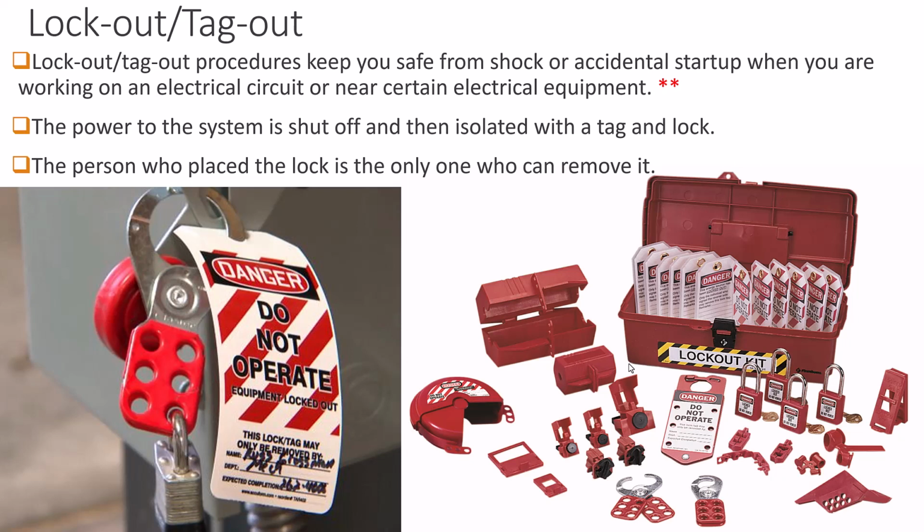But at some point, or maybe in many cases, you can only put 1 lock on a device, and maybe you can't do something like this. Well, then you can put that key inside of a lockbox, and then you lock up that key in the lockbox, and everybody puts their padlocks on the lockbox as a way to keep anybody else from accidentally, or when they're in some miscommunication, unlocking the device. And so this picture on the right-hand side is showing you a lockout tagout kit. But there's a lot of different kinds of covers, depending whether you have to lock a valve up so nobody can turn that valve back on.